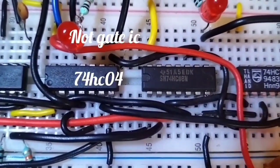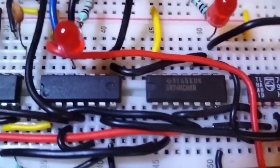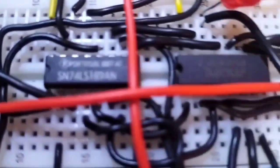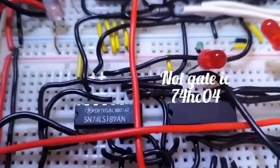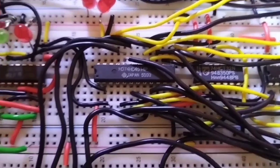This is the NOT gate used for the counter out and RAM address in control signals, which are active low signals, so we required it to invert. The next NOT gate we use for the RAM out instruction and also for the micro instruction register in.